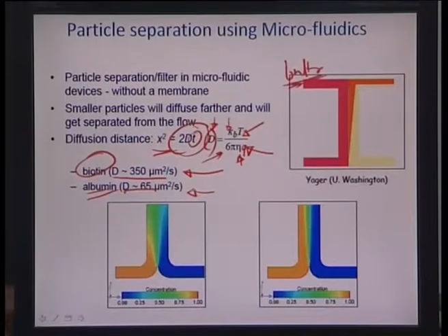How? Let us say you have two fluids here. This is a buffer solution which you are running through this particular channel, and there is also some kind of mixed solution which you are running here essentially from this end. And the idea is that as the flow goes past this, there is a phase separation, because the heavier molecule will not be that mobile in comparison to the lighter molecule. The lighter molecule here, as we assume, would diffuse towards this end, and will flow in this direction.